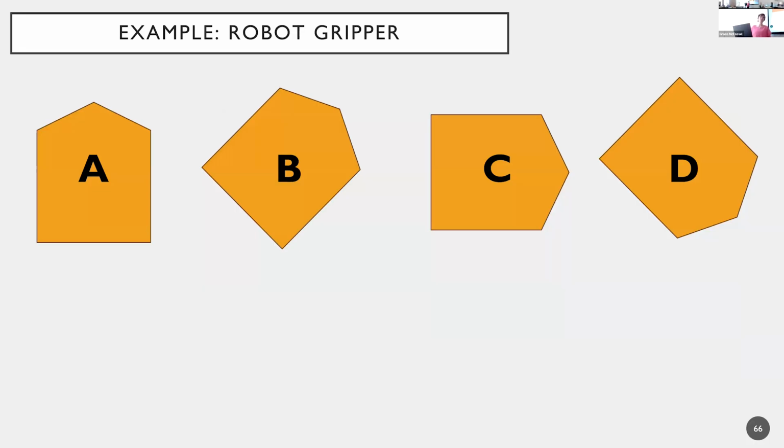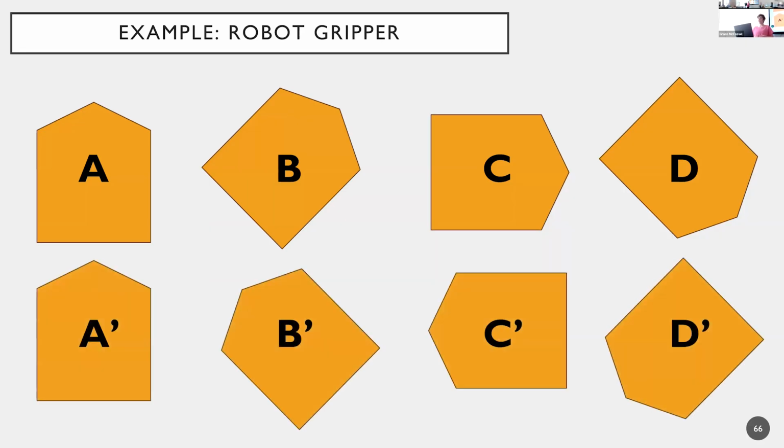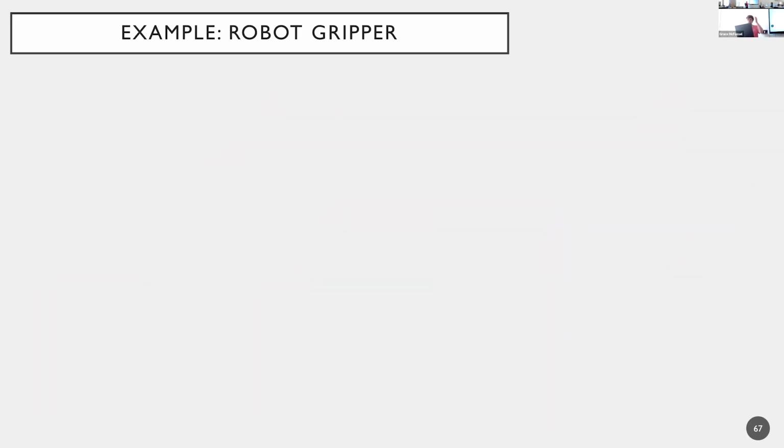Our part, when squeezed, will actually settle into one of 4 stable configurations, plus their symmetric counterparts. So while we start this problem with an infinite possible number of potential part configurations, the state space actually rapidly reduces in size, but it will never reduce down to a single state. It only reduces down to symmetry. So this problem can be solved completely without the use of sensors by executing memorized sequences of squeezes and rotations. And one example plan for it looks like this.